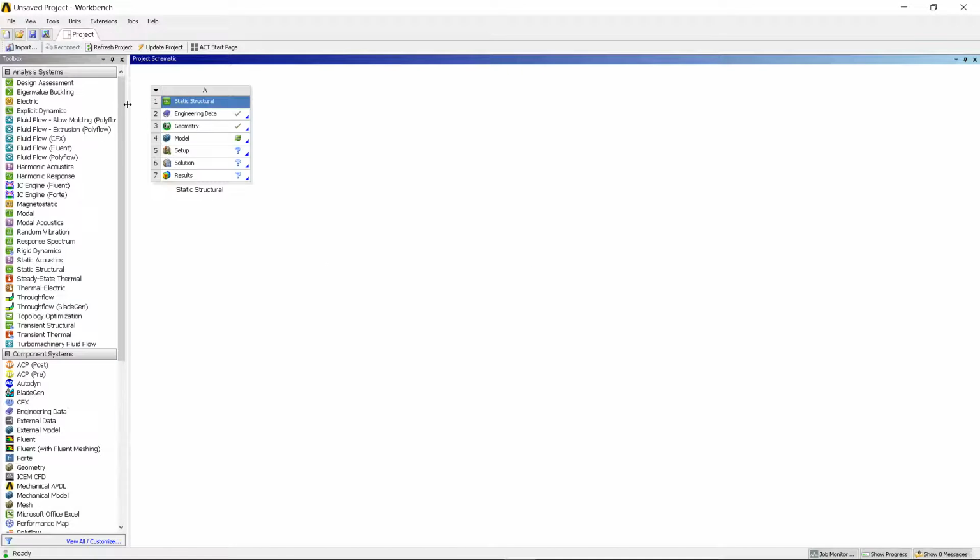Right? Let's minimize. Then after, it is time for the meshing. We can do meshing inside. Let's make it update, so that meshing will be done by default setting. We will see in detail what type of meshings are there, how the meshing affects and what is the quality criteria for the meshing. Meshing is very important, it influences the end results. Based on the processing power, you are supposed to do the analysis for the meshing.